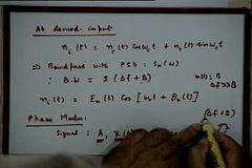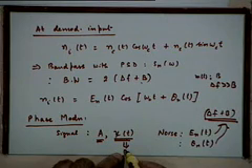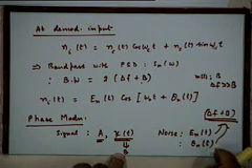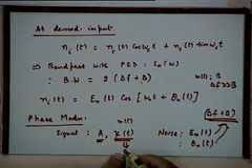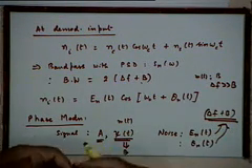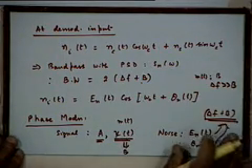Sir, aren't e_n(t) and theta_n(t) both low pass? They are low pass, but they are low pass with a much wider bandwidth, right? This is also low pass. This has a bandwidth of B. I am comparing low pass signals, actually three of them. This is m(t), which has a bandwidth of B, and these are the noise. Their bandwidths are very different, so their properties are different. That's the point I am trying to make. These will fluctuate more rapidly, this will fluctuate less rapidly. This is a point to keep in mind as we proceed.